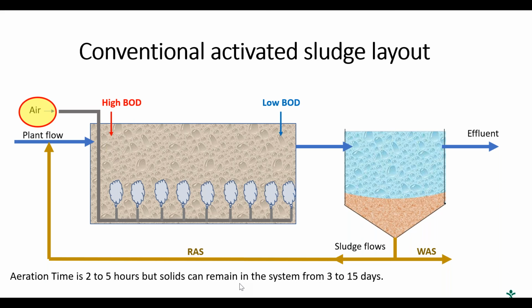And I'm showing you the most simplified diagram of an aeration tank, where all the loading is at the beginning and it continues to the end and then to the clarifier. There's lots of different ways that these things can be fed, but this is the simplest way to show it. The concept is the same, but just know there's lots of variation. There's step flow, for example, different kinds of ways that it can be fed. Still, the F-M ratio and the MCRT that we're going to look at today are still relevant to all those different variations of activated sludge plants.